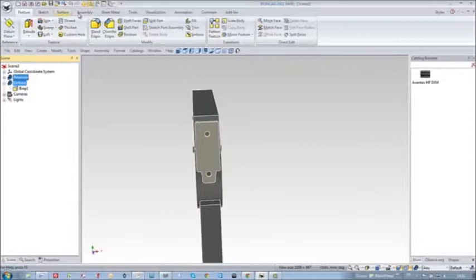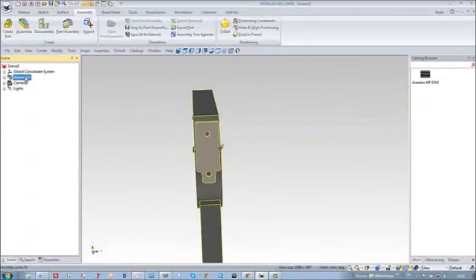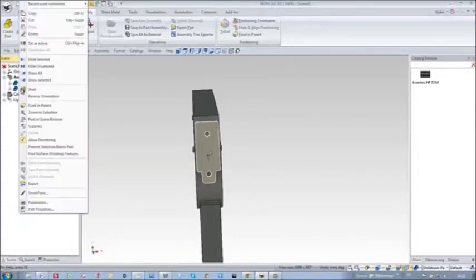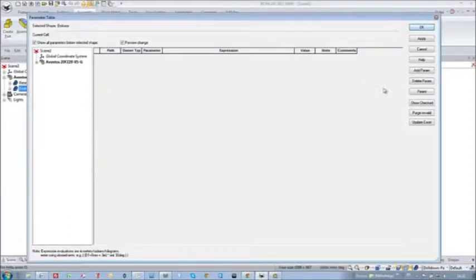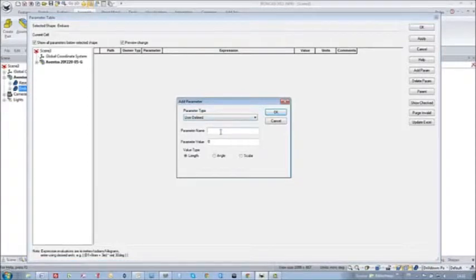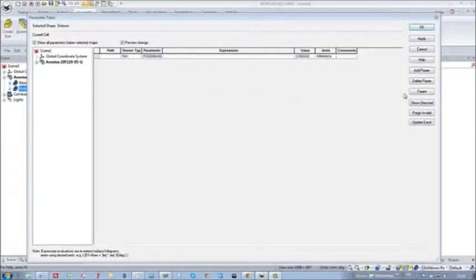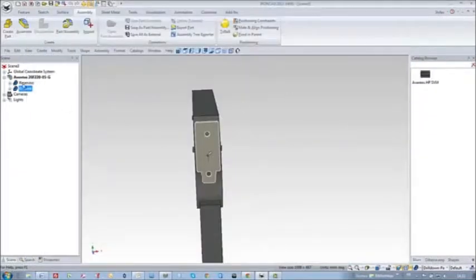Now I'm going to assemble both parts to make only one assembly, because it's only one hardware in my virtual library. And I rename it to the corresponding Aventos name. Since my M-base must automatically move downward, I can achieve this by creating a new variable. So I create a pose M-base variable. I leave it at 0 at this stage of my design.